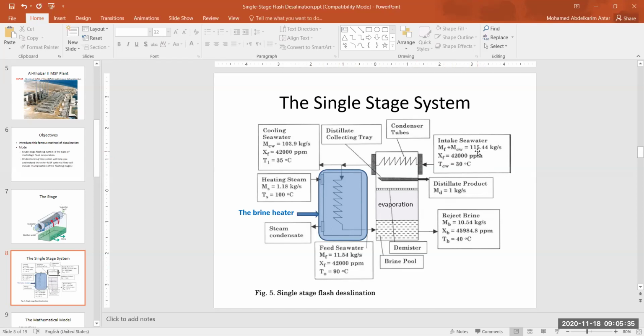This is a tremendous amount of water coming in. As it gets here, it will be preheated, and vapor is going to condense. The big quantity here is just to make sure that all the vapor which is rising here by flashing is condensed. And when it condenses, this whole quantity is going to help produce only 1 kilogram per second of water.